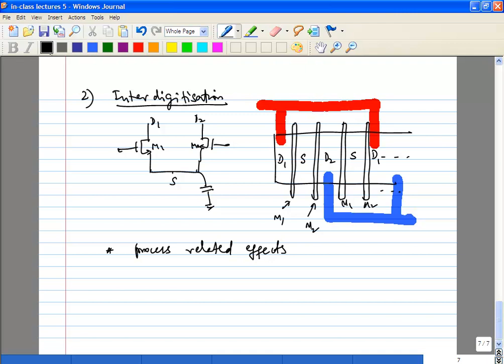If you just lay it out as two huge bulks and you don't know which way the wafer is going into, let's say, the furnace, what that means is there will be temperature gradients. Similarly, let's say they're doing some deposition of the dopant, it will come from a certain direction, and it may not be uniform. Those are all things you have to worry about when you want matching, and if you do something like this, those kinds of effects will be distributed out.